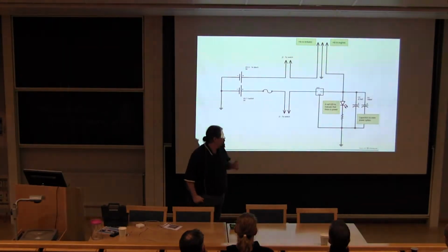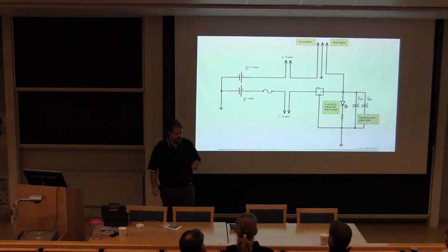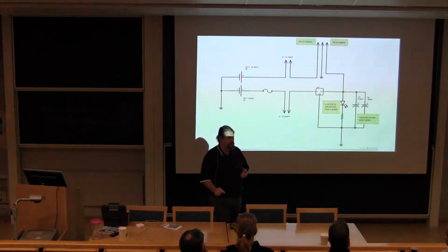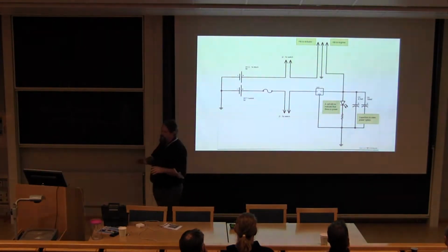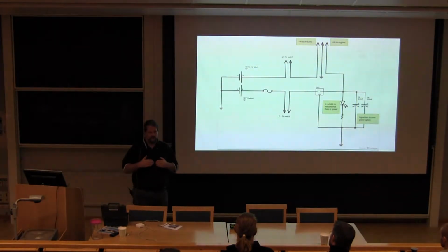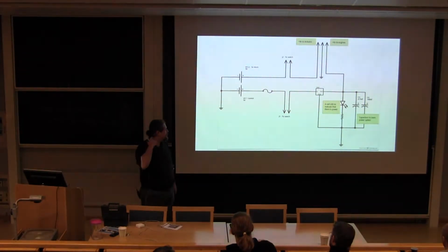I also see 2 capacitors between that. A really big one, which was the biggest one I could find lying around unused, and a small one. This is because when you start or stop the engines, they will draw more or less power. And to even out this power, you have the capacitor filtering out the spikes in the energy.